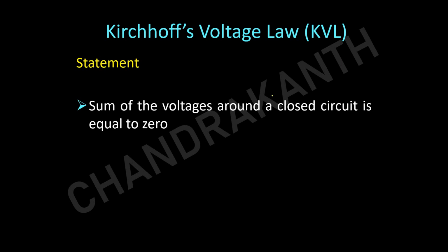So for this KVL, this is a very important point. The circuit should be a closed circuit. We cannot apply KVL to an open circuit. In short form, you can represent this as summation of voltages, that is sigma V equal to 0.